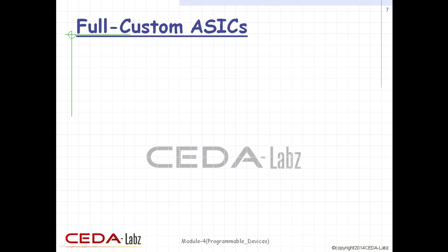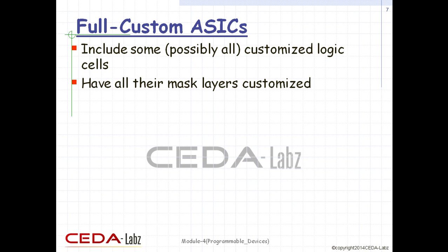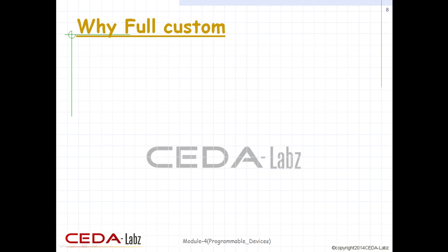The type of ASIC we are going to discuss is full custom ASIC. In a full custom ASIC, the designer will design all the logic cells and layout for a new application. The designer will not use any predefined cell in this approach of designing. Each design is customized according to new specification. So, 90% of the cells in this type of designs are a first-timer.